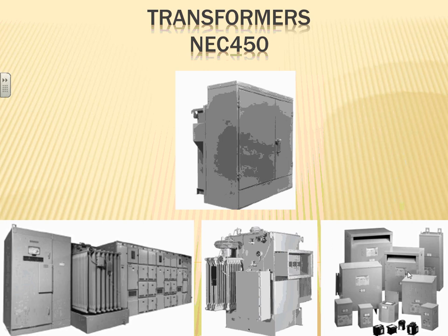So that's the most common transformer that you get engaged in sizing, right? Other than the receptacle transformers, what we call 208/120 transformers, we don't typically size the utility type. Do you? Some on the medium voltage. Okay. Then you get into that big boy here. That's a substation type transformer. Now we get into the medium voltage and the higher volt amps.